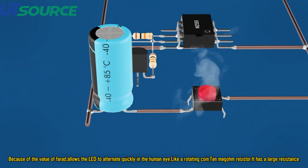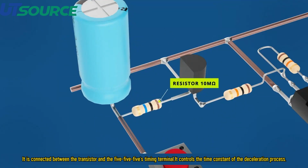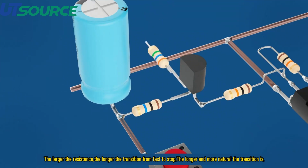10 megohm resistor. It has a large resistance. It is connected between the transistor and the 555's timing terminal. It controls the time constant of the deceleration process. The larger the resistance, the longer the transition from fast to stop, and the longer and more natural the transition is.